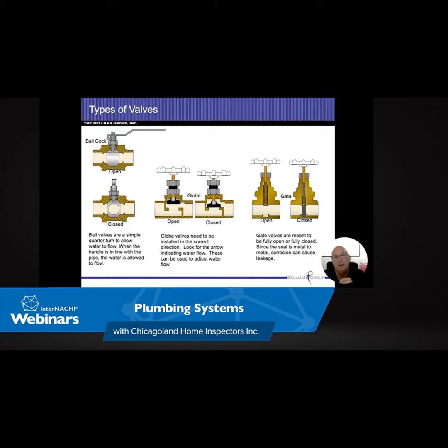Sometimes we'll see a whole house chamber as well. Those get damaged, and again, the air gets absorbed into the water, and then the water level keeps rising when it gets up in there. Simple solution to those two is you just drain your plumbing system. So shut off your supply lines coming in, or your service line coming in.